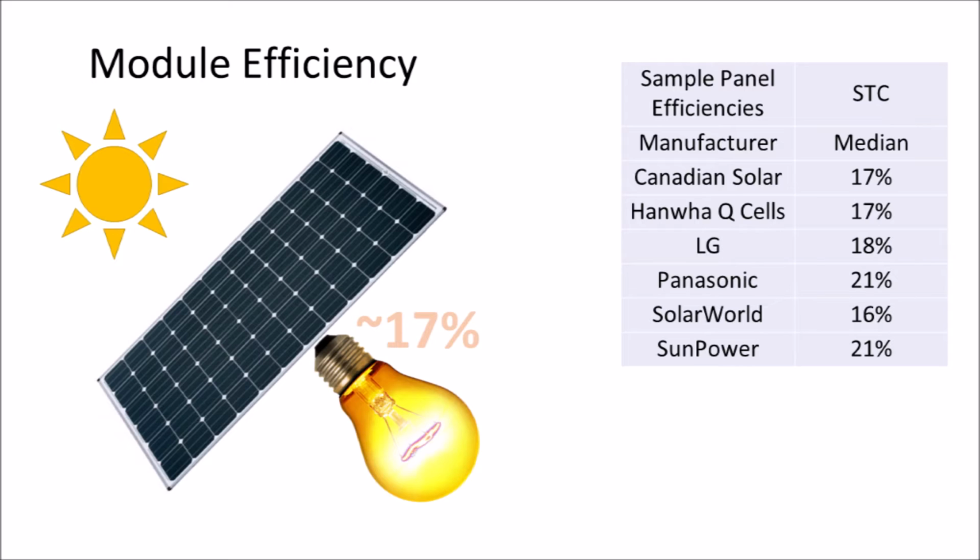So scientists themselves have underestimated how much electricity can be squeezed out of the annual incremental improvements in solar module design. For example, a recent advancement in silicon is called PERC, which makes the bottom of the solar cell more shiny. This additional reflection increases the total solar panel efficiency by 1%.